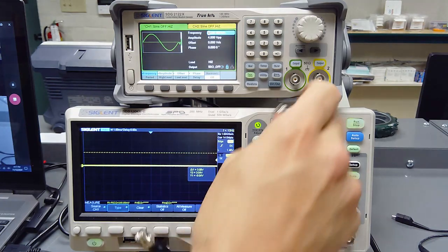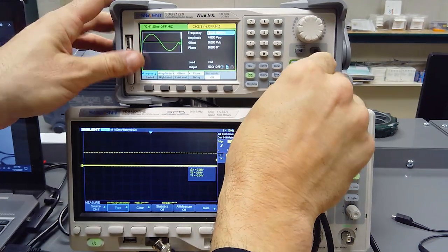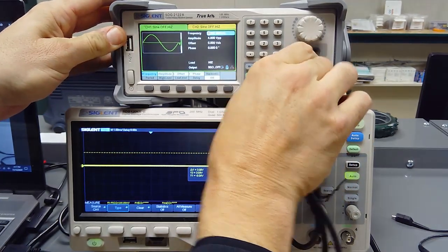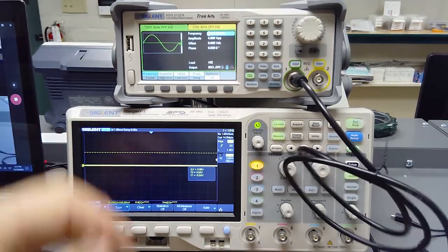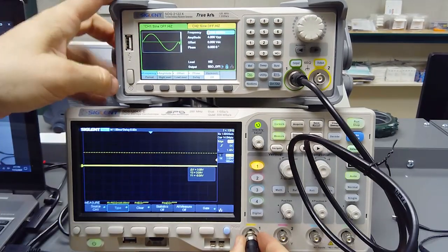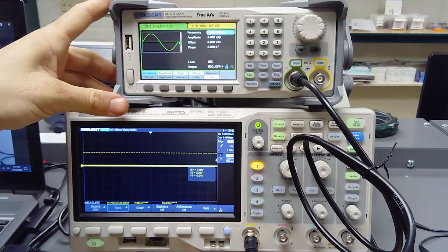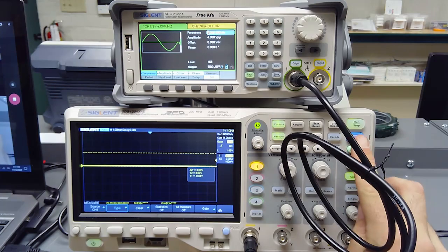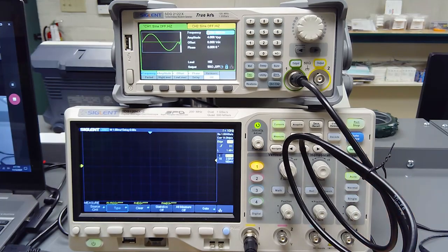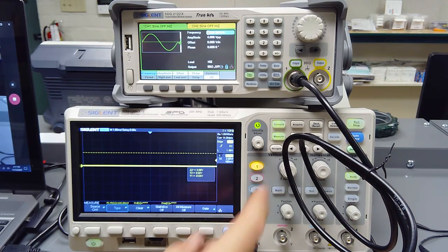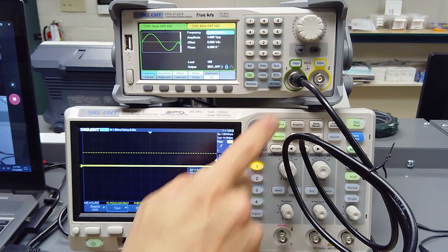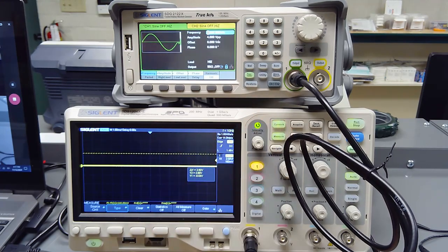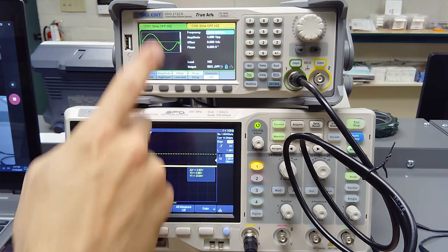So I'm going to connect it to, this one has 2 channels, I'm just going to connect it to channel 1. And then I'm going to connect the other side of it to channel 1 of the scope. Okay? All right. So for right now, I'm going to hit the auto setup button, which shouldn't really display anything, but we have 1 channel visible. We have the cursors here, which we'll use later. And now I'm going to go to the function generator.